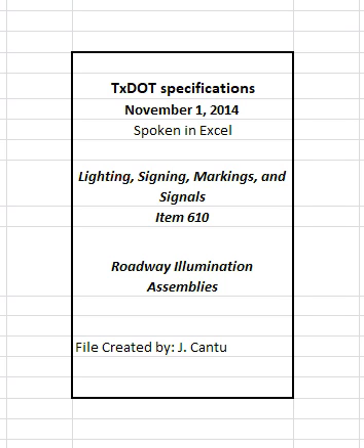3.2 Relocation. Relocate roadway illumination assembly components in accordance with the details, dimensions, and requirements shown on the plans. Do not use screw-in type foundations. Install existing structures on new foundations in accordance with section 610.3.1, installation. Do not place grout between base plate and foundation.